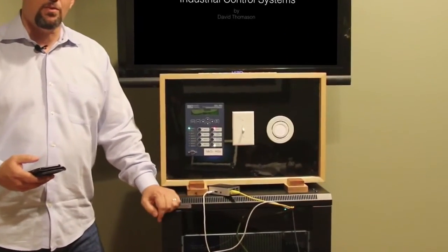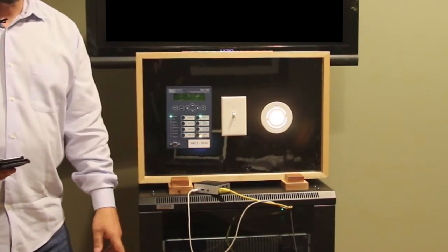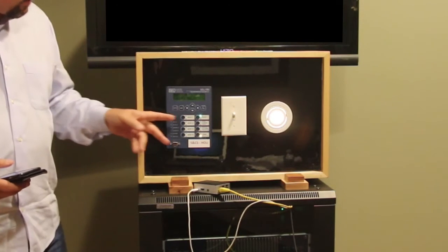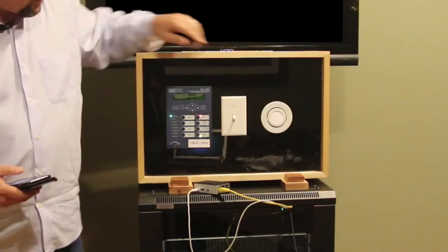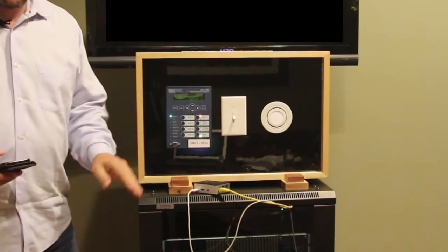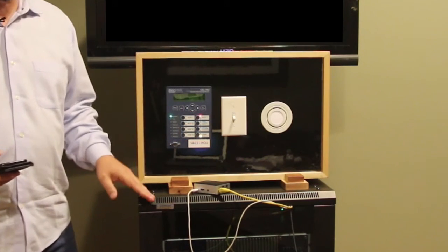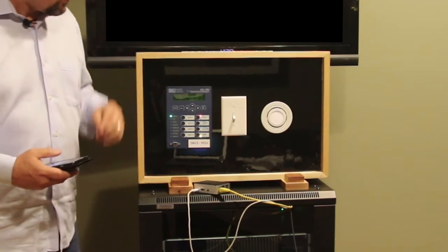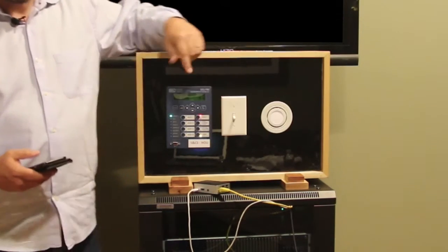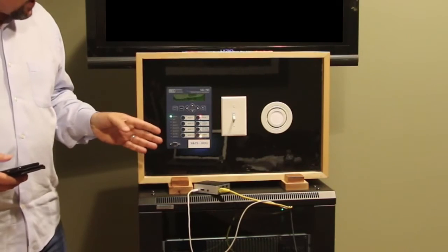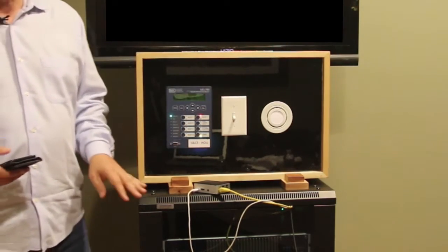So what happens is when there's power in the substation, the RTAC down below will communicate to the relay to say that there's power, and it will be indicated with a green indicator light. When the power is turned off, the RTAC is also sending messages to the relay saying the power is off, and indicating that with a red LED indicator light. So it doesn't matter how many times we turn this light on or off, that light is going to switch only because the RTAC down below knows whether there's power to the light or not.